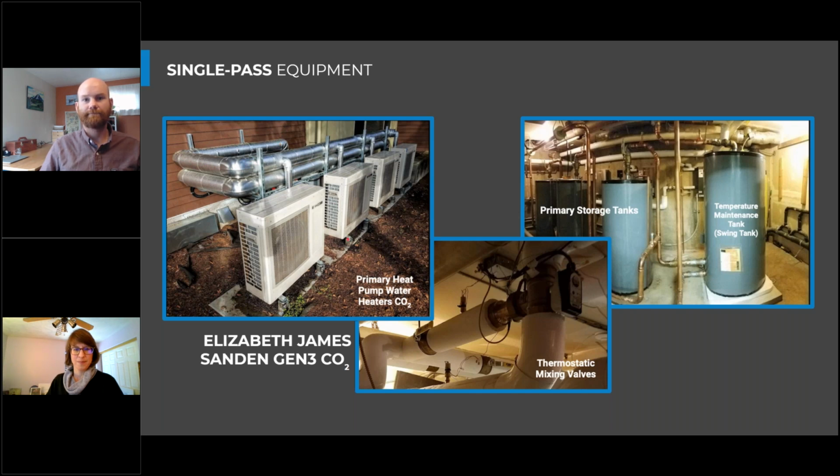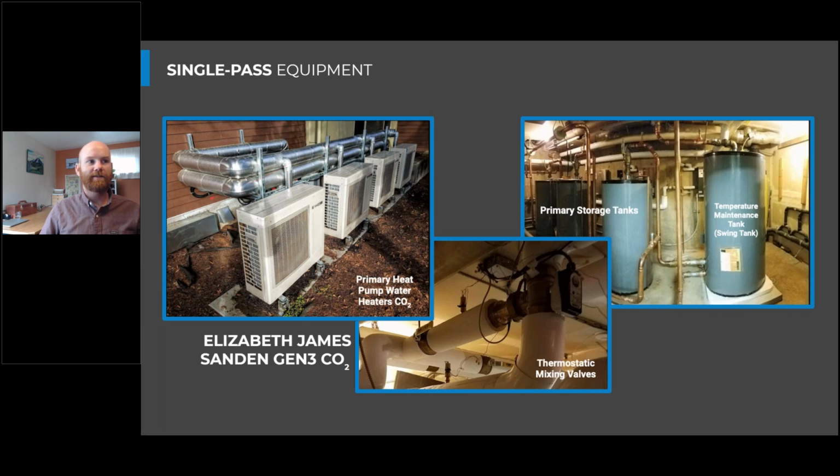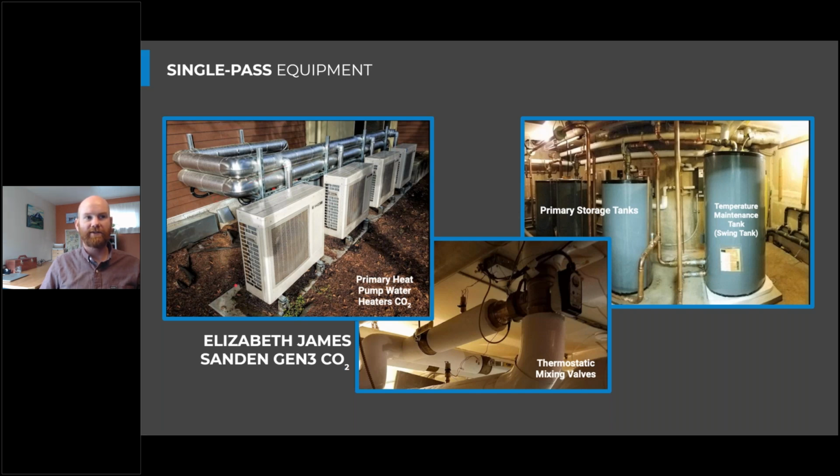Great. And this is one way to really address freeze protection, because we now have these heat pumps outside. Seattle gets cold. It snowed 16 inches up here in North Seattle a year ago, and we need to protect those from freezing. And so we can insulate them with a little bit of extra insulation, and the periodic use is enough to keep those above freezing temperatures and prevent us from putting a freeze protection heat trace tape product on those piping legs.